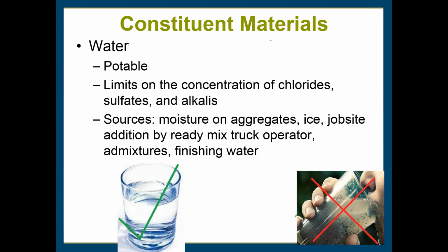Additionally, if it's really hot out, your aggregates have microscopic little pores on them. They're porous. They can have water inside them. They can have water on the surface. And that's something that we'll get into in more detail in PQS. It's kind of interesting, actually. But if it's really dry, those aggregates, when you put them into the mix, can actually absorb some of your mixed water and alter your water to cement ratio and drop it. And that's something else that we have to account for.